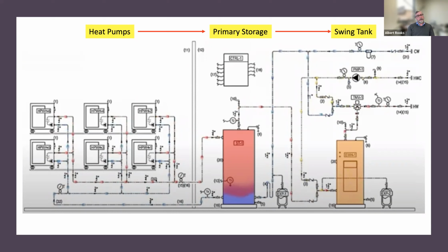If the heat pumps are connected directly to city water, we can't really run that circle, right? We want to be able to, in a no load condition, like an overnight condition, where there's very little draw, just take the volume of the tanks, which may only be 50% full of full temperature water, or they may only be 25% full, but we want to be able to run that circle. And so that's why we connect city water into the stratified tank and then out of the stratified tank to the heat pumps so that we can fill the primary storage from top to bottom. Hopefully that makes sense to everyone.